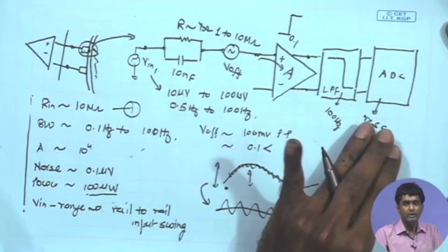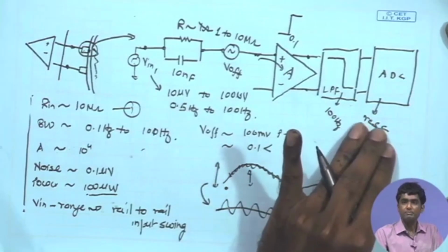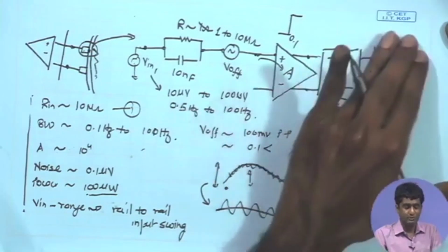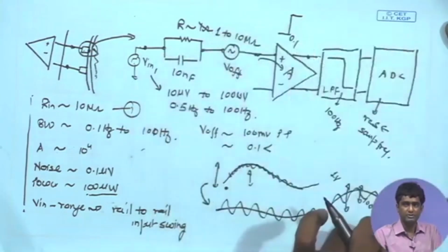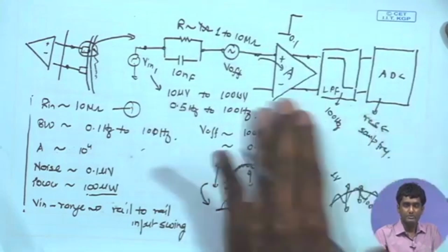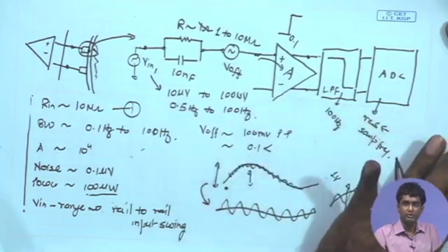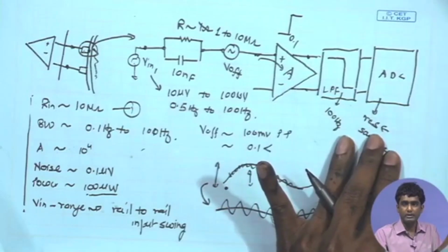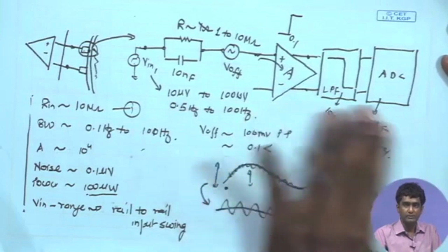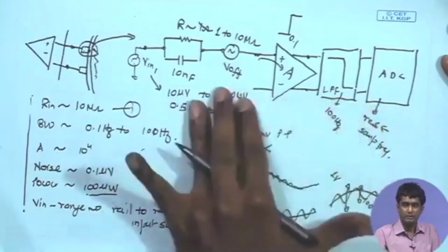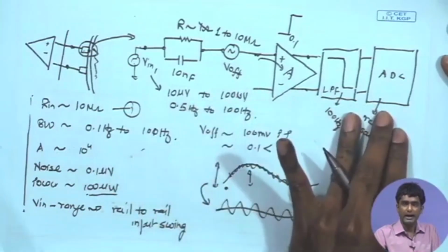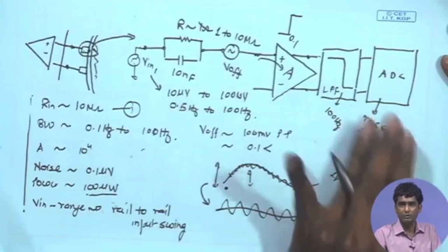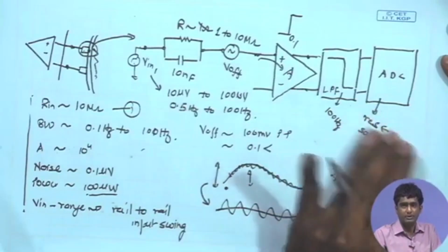And although in power management people generally take care of that by isolating the power supply of the analog domain and the digital domain, you have a common substrate. You are going for a mixed signal design where you have a common substrate, and in general the capacitive coupling between those digital signals and the substrate will propagate noise along the analog part of the design as well, and as a result there is a high chance that the ground and the VDD will also have that kind of noise coupled with them.